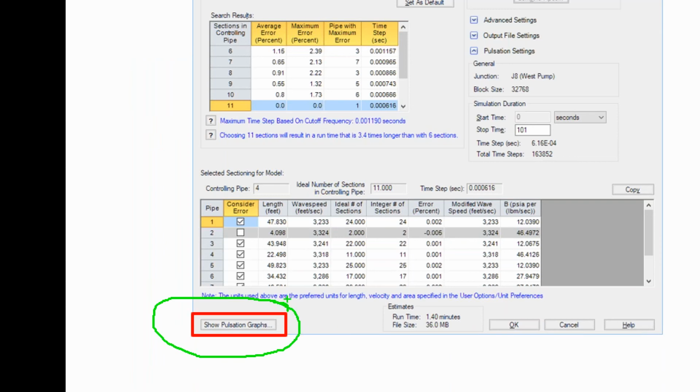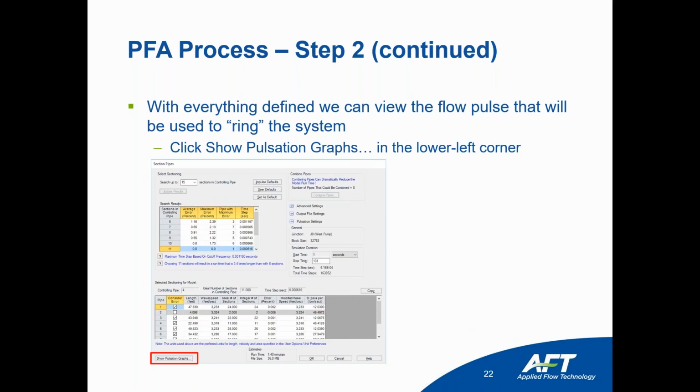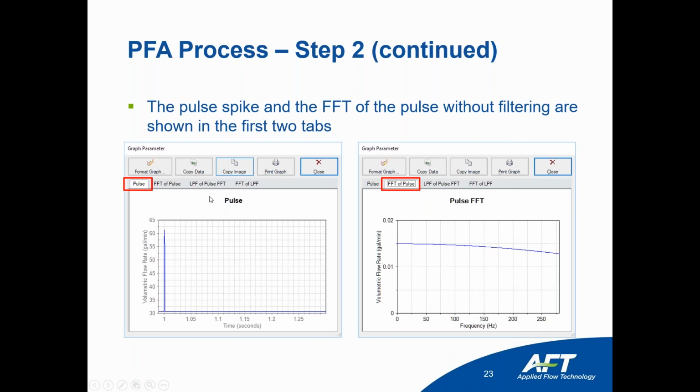Some pipes can be excluded from the analysis, and the reason for this is that not all the elements in the model are pipes. So in this case, P2, P8, and P9 are volume elements, and they're not real pipes. These are the bottles, so you don't have to include them in the analysis. And also P10 is acoustically isolated by the centrifugal pump.